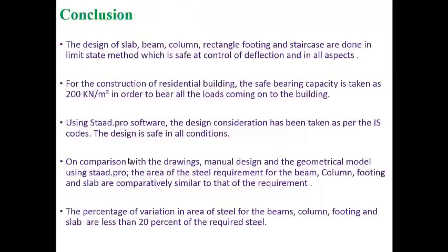Conclusion: the design of slab, beam, column, rectangular footing and staircase are done in the limit state method, which is safe with control of deflections in all aspects. Using STAAD Pro, the design consideration has been taken as per IS codes. The design is safe in all conditions. The percentage of variation in area of steel for the beam, column, footing and slabs is less than 20% of the required steel.